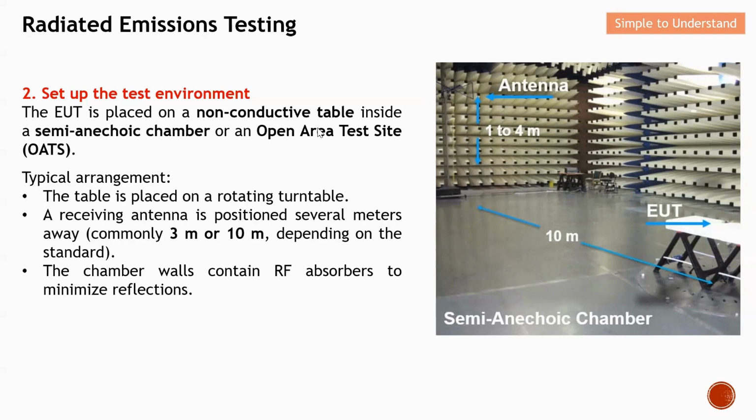This is pretty rare now, because we have a lot of signals, cellular signals, etc. Therefore, it is very challenging to conduct radiated emission testing in an open area test site now. Rather than that, most of the time I believe we do the radiated emission testing in a semi-anechoic chamber.